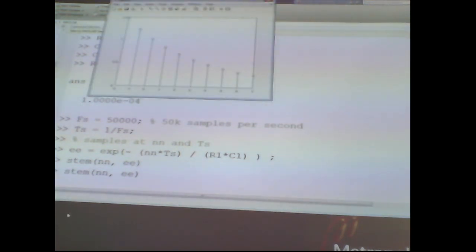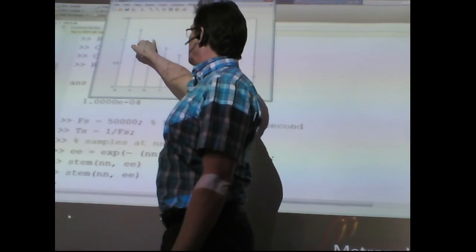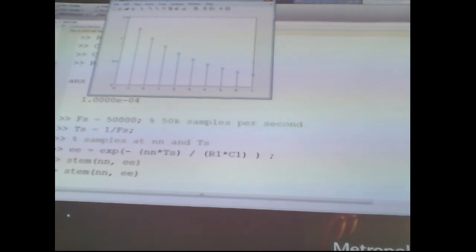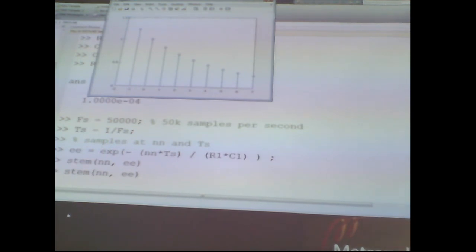Okay, there's something wrong with this picture. If this was a test of an RC circuit, and you would compare this with your measurements, the data is starting from negative times. Usually you set the edge of your test vector starting at that point. But now we have a couple of extra points. And that's where you would use the Heaviside function, the step function.